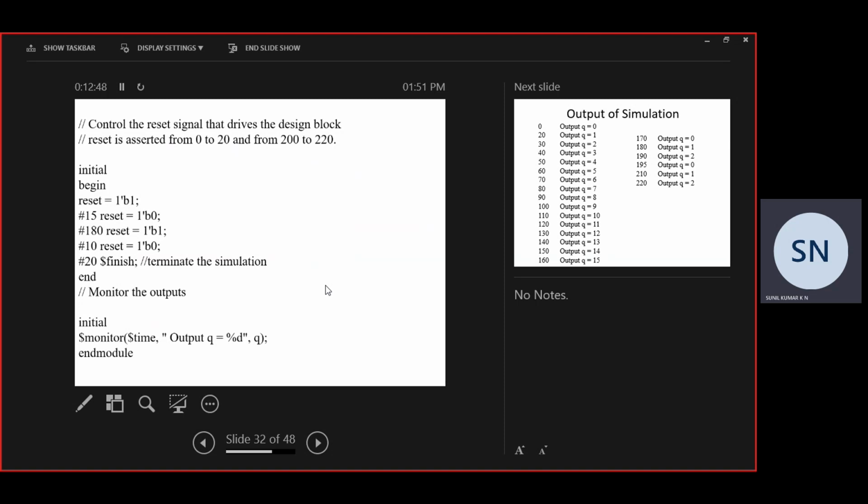This is nothing but decimal 1. The value has been incremented by 1 because it is the first clock signal, and at the previous clock Q was 0. Through the inverter, D had an input of 1. So whenever the negative edge comes in the next clock cycle, it is going to increment the value by 1.